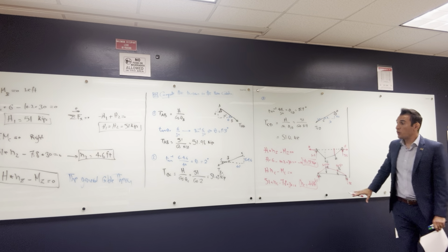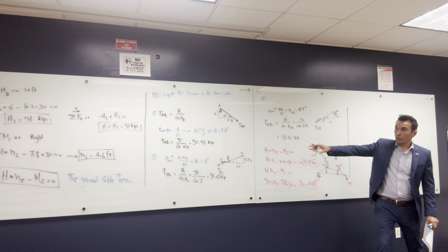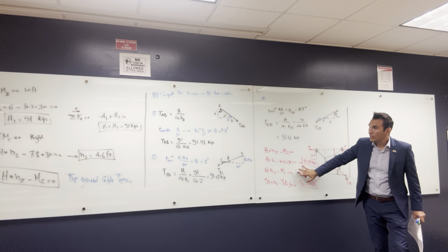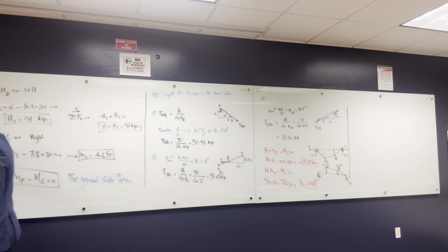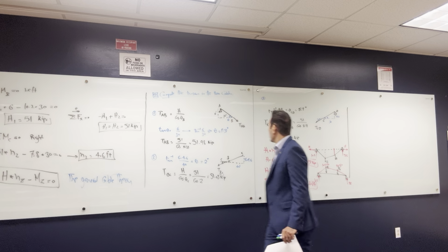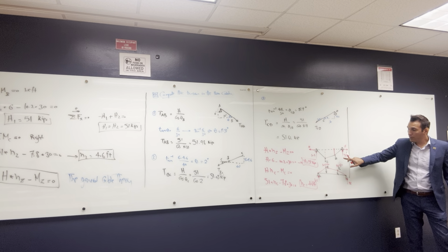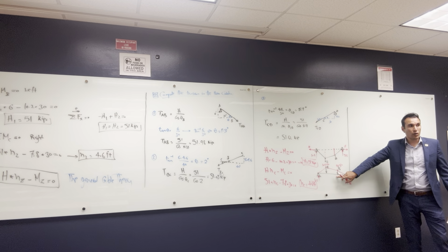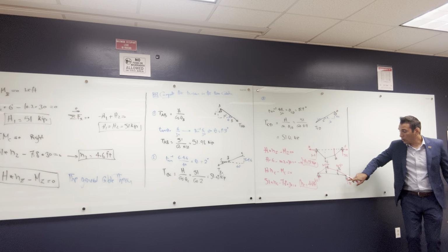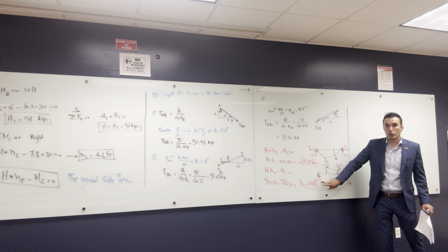I solved this problem in just 2 steps. The whole thing, all what we did right now, I did it here, all these 2 parts, here and here, from static equations. How? You draw the equivalent simple beam of the cable, put the same load on the cable at the same location on the beam. Get the bending moment of this beam at these 2 points. Solve this beam for reactions. I got these reactions here, 7.8 and 10.2.